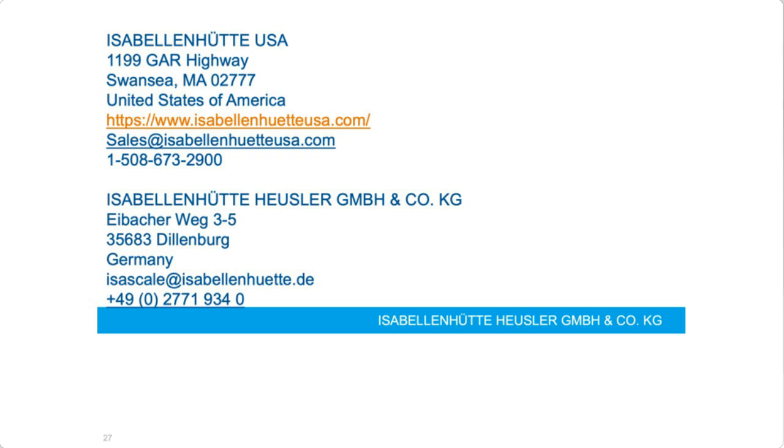And then the IVT 3.0 Pro, which also comes with the isolation monitoring and the voltage sensing, has an ASIL B rating on both of these functions. So it is ASIL-C for the primary current sensing and ASIL-B for the voltage sensing and the active isolation monitoring. And then the redundant secondary current sensing channel that this product offers has an ASIL-QM rating.